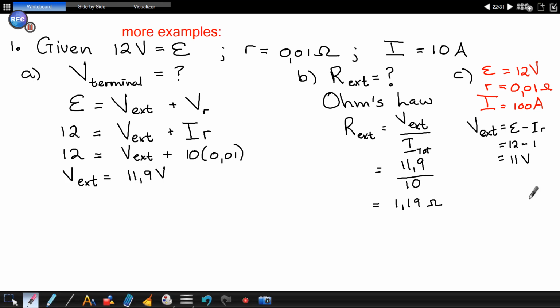The big question is, why would the current increase like this? What must happen in the circuit to increase the current? The resistance must decrease. Okay. So question D says, explain why the lights of the car dim when the car is started while the lights are on.